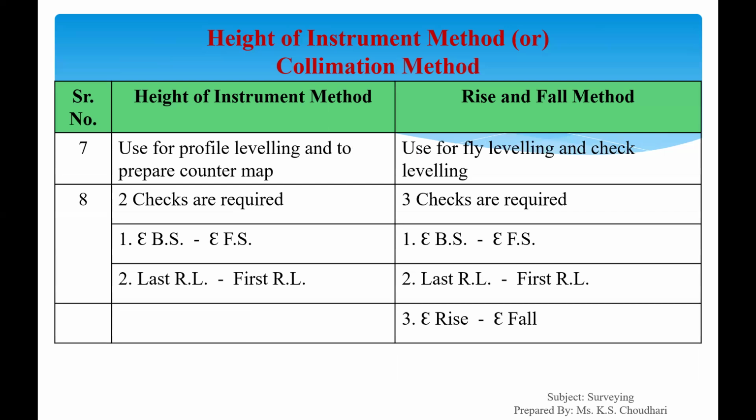Height of instrument method is used for profile leveling and to prepare contour maps, and rise and fall method is used for fly leveling and check leveling.